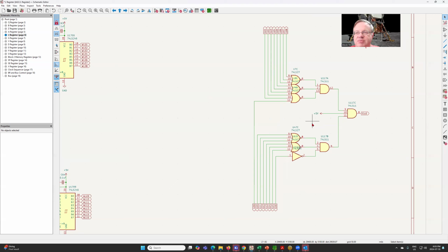So this is just, again, because I've got space, and the L register doesn't use up the full board space, so I'm just going to add this logic here. In this case, you can see there's a 5 volts. Well, why didn't I just use a 2-input AND gate? It's because the 74LS11 actually has three-input AND gates on it, so I'm able to save adding another chip. I believe the other chip is the 74LS08, which is a quad 2-input AND gate. So this saves us from having to add another chip and allows us to use the third 3-input AND gate that we have on this chip.